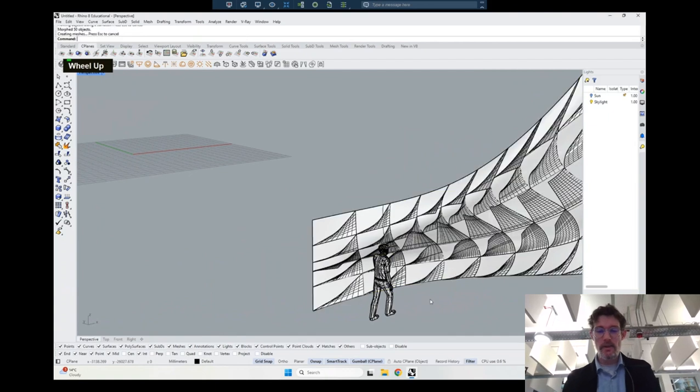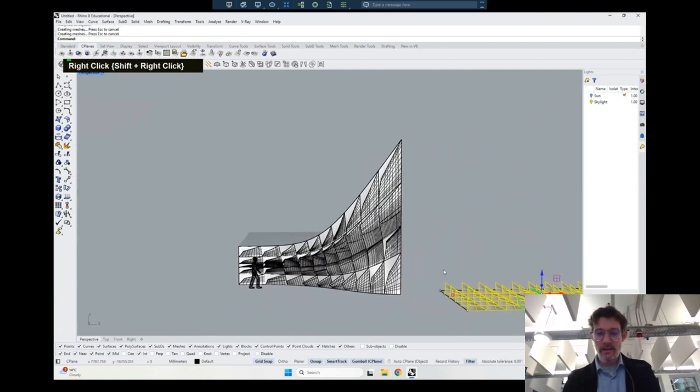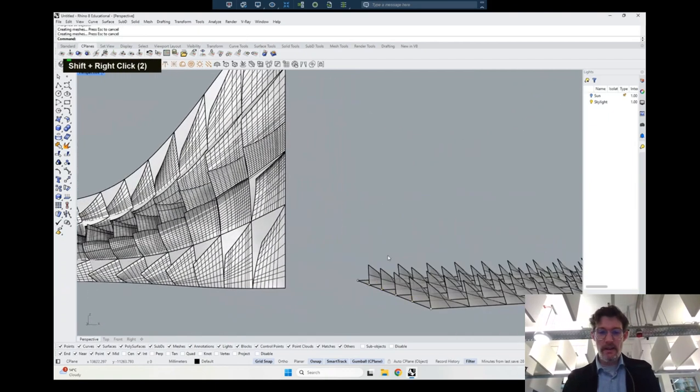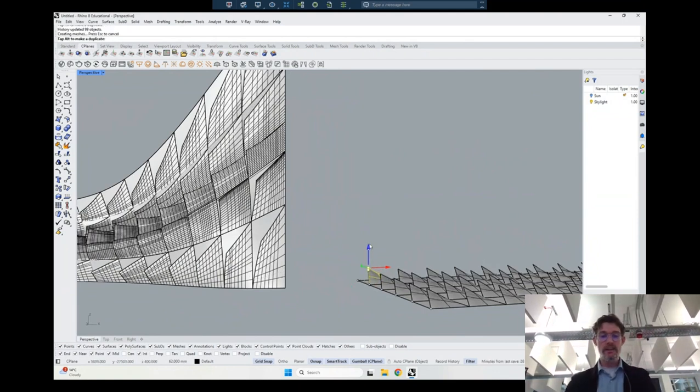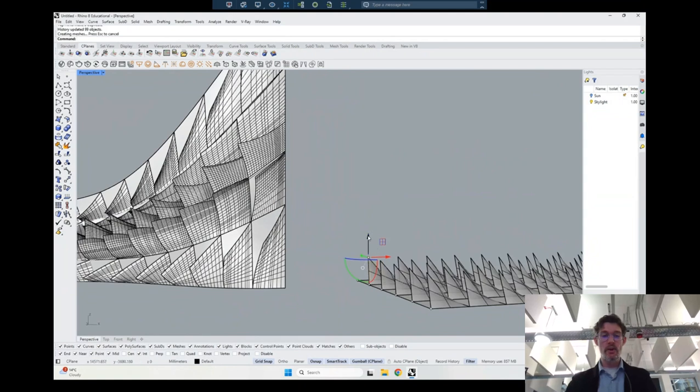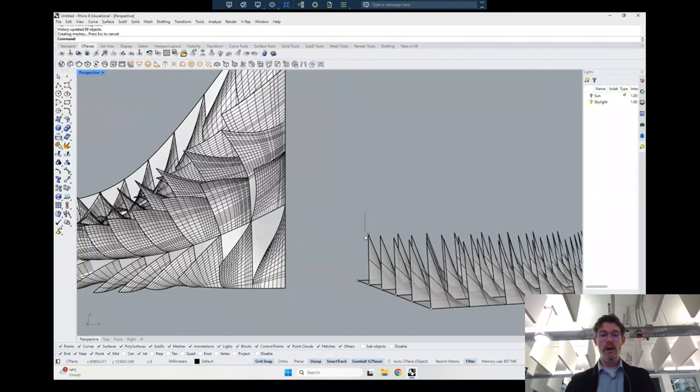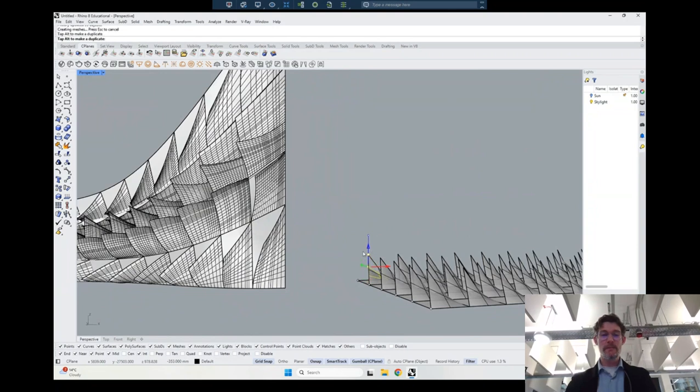There we go. And now, what's going to happen is I come back to my original object. I press F10. If I adjust this, the first thing that's going to happen is it's going to adjust all the arrayed children copies. And then it's going to remember that those copies are then flowed along the more complicated surface. So basically, I now have the ability to control everything with one click of a mouse, which is kind of fun.